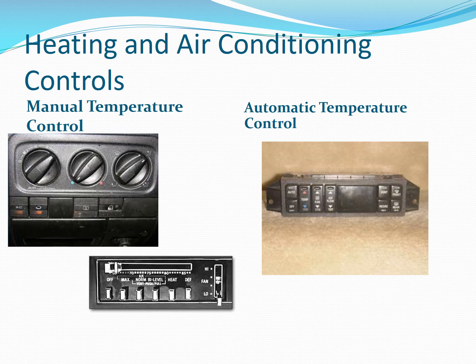But you still had to physically select the mode and the fan speed. So that's a semi-automatic system. Picture on the right, that is a fully automatic system. Obviously that's taken out of the vehicle right now, but in that black screen you would see the temperature that you are setting it at, and then based on the sensors placed throughout the interior of the vehicle, the car is actually going to automatically control the mode, the fan speed, and the blend of the temperatures over the heater core or the air conditioner evaporator to achieve the temperature that you set it at.